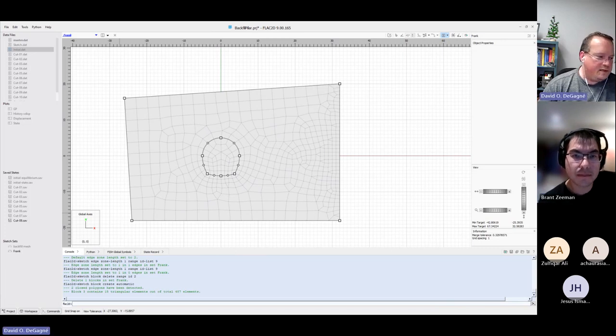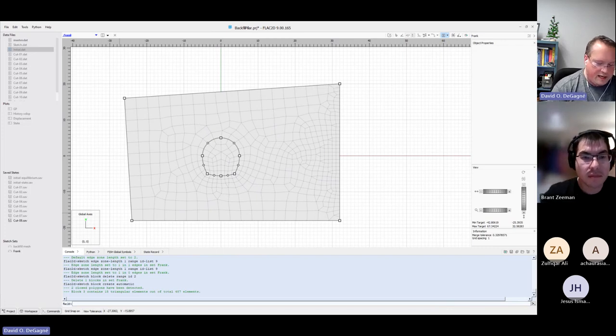Well, in the problem set, we've assumed that you're going to excavate in 6-meter increments. If you want to change that, you kind of have a couple options. If you went smaller, then I wouldn't be worried about numerical instability because I know it works for 6 meters. But if you just took out, what is it, 72 meters, say you took out half of that, there'd be other things that we would add to the model to ease the model into that.